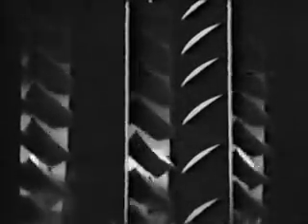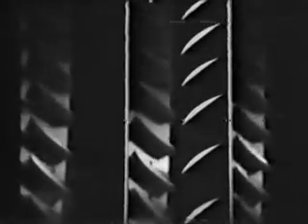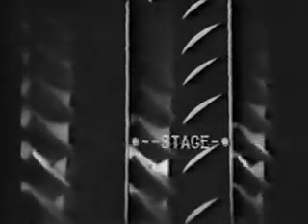Small amounts of compression occur between each set of rotors and stators. Each pair of rotors and stators is a stage, and this compressor has 11 stages. At each stage, the rotors speed the air up and the stators slow it down. In slowing the air's velocity, the energy from velocity is transformed into a slight increase in pressure.